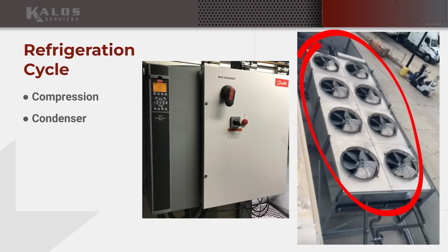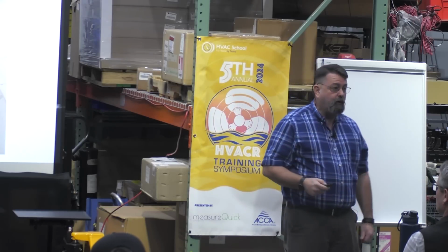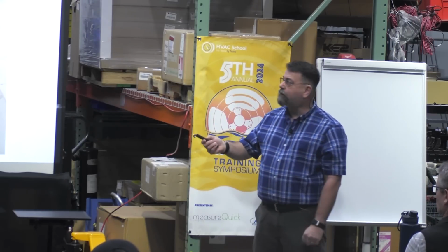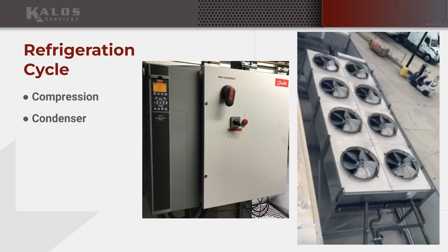The other thing that we've got is a whole bunch of fans. Well, we may have 2. We may have 12. Totally depends on the application and how large this rack is and the ambient that it lives in. Miami will have 2 more fans than we will in Michigan. It's just how that works, okay? So when I look at this, the other thing we're going to add to this, once again for that lower ambient setup, when it gets cooler outside, I'm going to start turning off fans. I'm going to stage my fans.